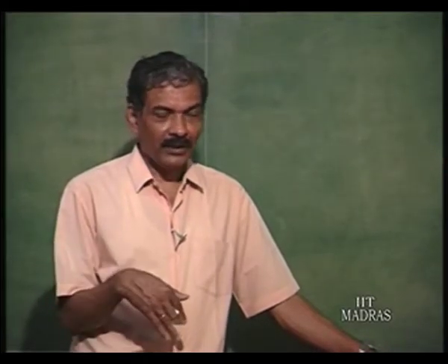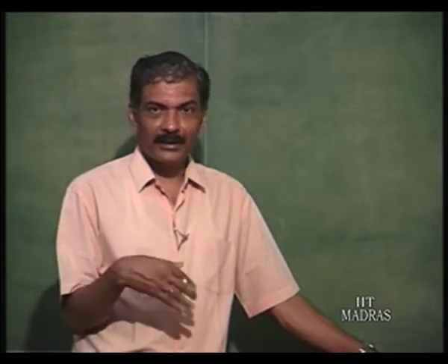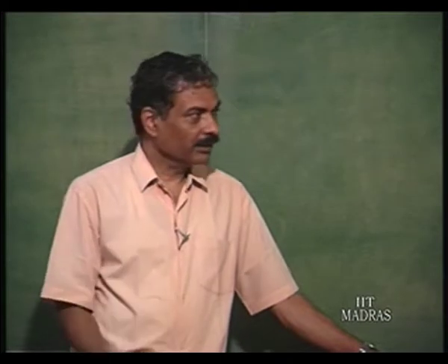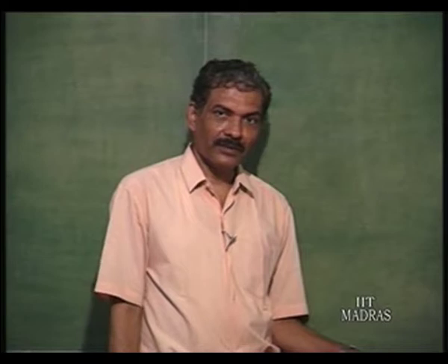Once averaging is involved, you have to wait until the average is created for you to get the accurate value of the product. So, this particular circuit is usable only for low frequency application.